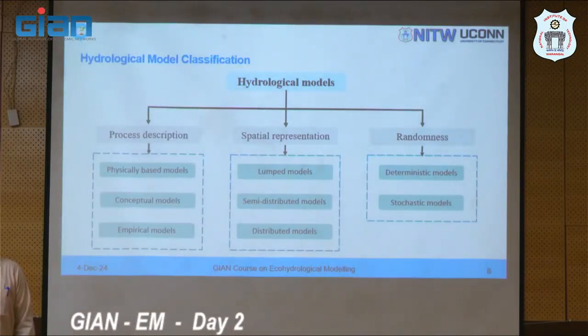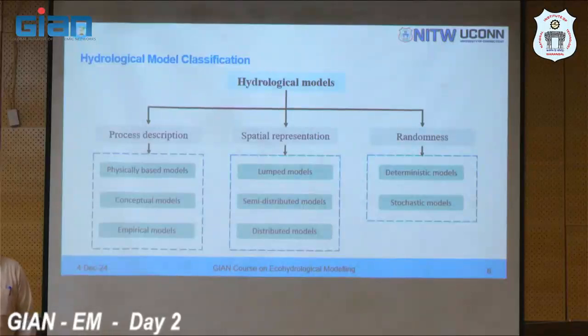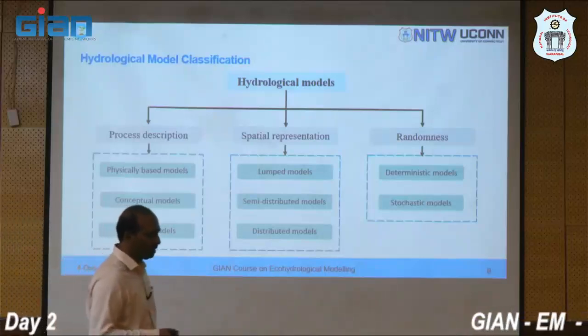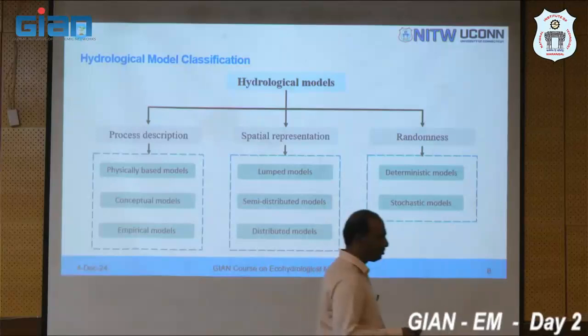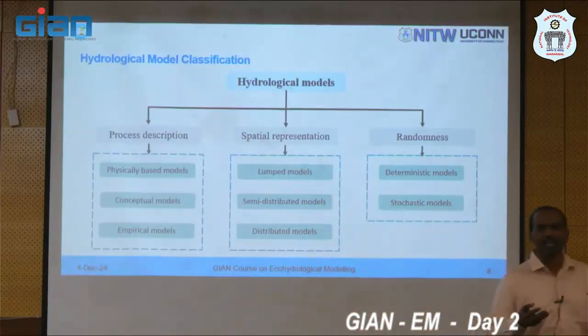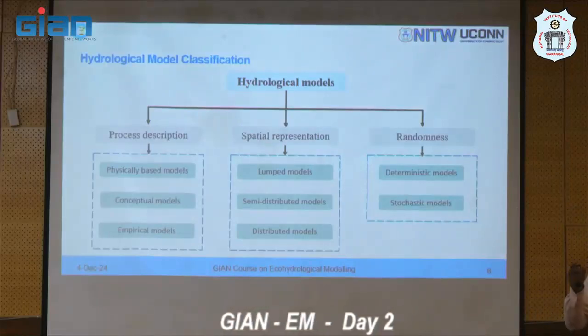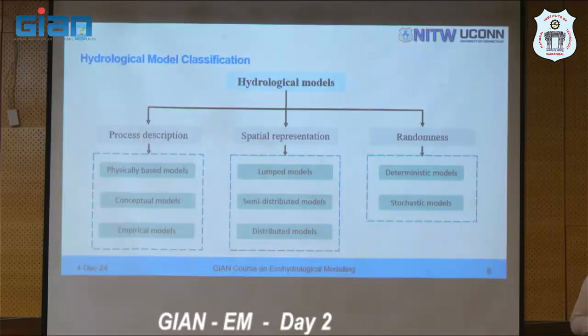Now, at a watershed scale, how do we apply the SCS curve number method? If you have different land use and different soil classes, we take a weighted average curve number. Yes. So, what are we doing by taking a weighted average curve number?